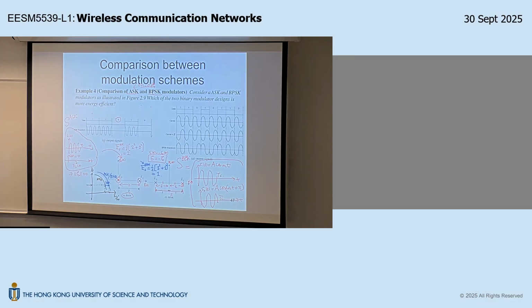So we talk about binary. So what about 4 points, right? So QPSK, quaternary phase shift keying. The constellation, so the signal set, if I express directly in the signal space, is of this form. It's a 2-dimensional space. This is I, this is Q. And then the 4 points are like this, forming a square. Okay? So this is the constellation design for the QPSK.